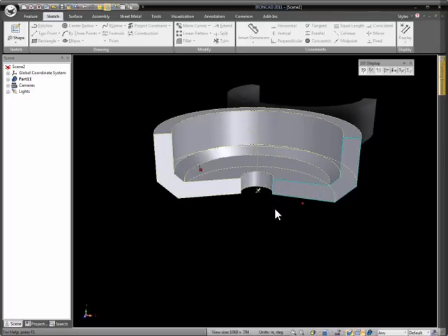So it really depends on the user's preference whether they want to actually add those constraints and allow modification with handles in the basically in context design, or if they really want it to be parametrically set and defined and not allow the users to adjust it freely in that regard. That's just from the sketch level. In addition to the sketch, you can always use direct face modeling to modify the geometry at will as well. That would, again, remove all your constraints. But that's a user's preference, but something I wanted to cover for some of the newer partners.